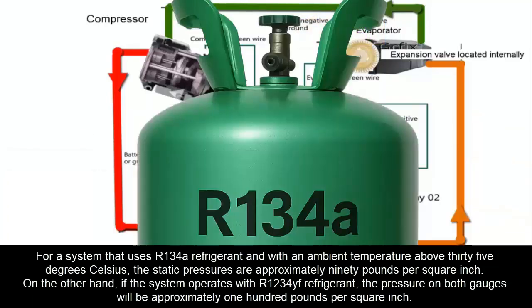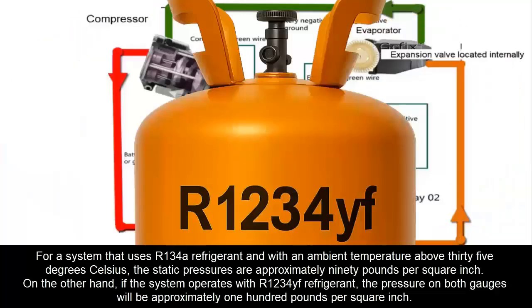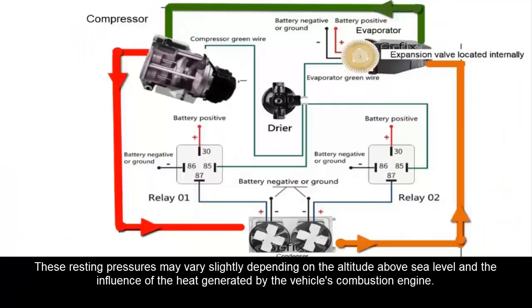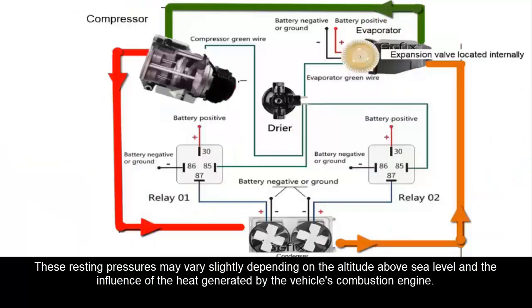For a system that uses a 134A refrigerant and with an ambient temperature above 35 degrees Celsius, approximately 95 degrees Fahrenheit, the static pressures are approximately 90 pounds per square inch. On the other hand, if the system operates with our 1234YF refrigerant, the pressure on both gauges will be approximately 100 pounds per square inch. These resting pressures may vary slightly depending on the altitude above sea level and the influence of the heat generated by the vehicle's combustion engine.